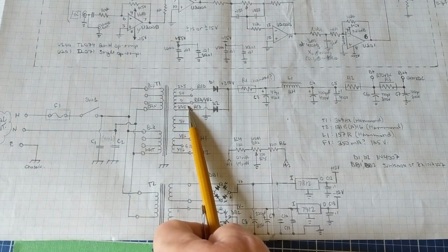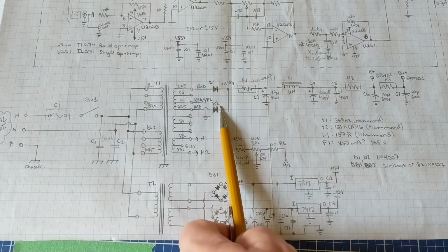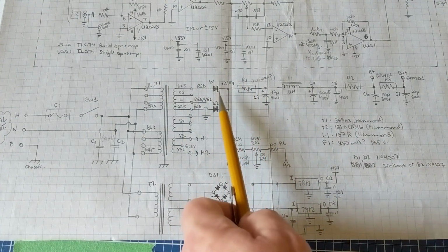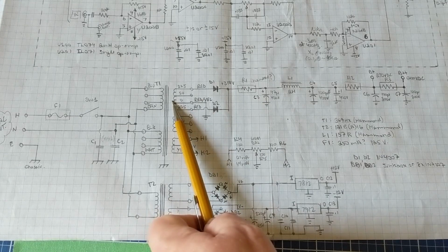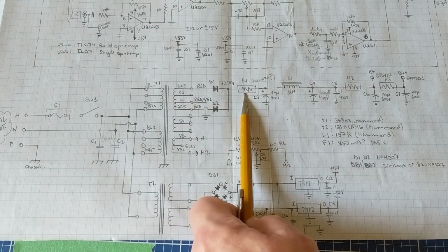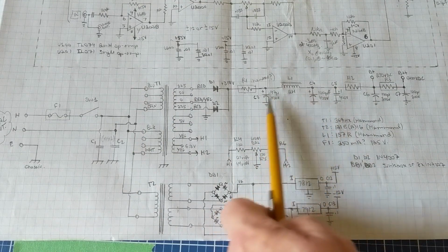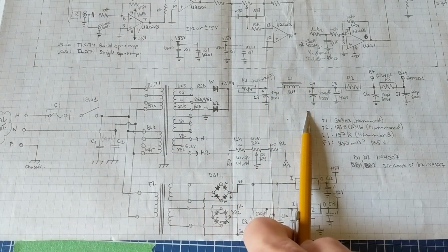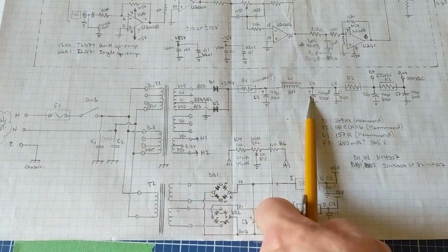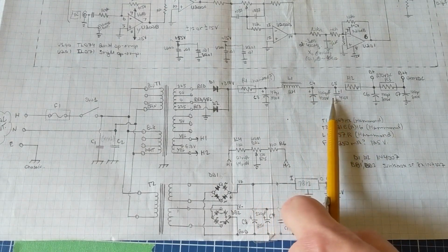For the high voltage tap secondary, I'm using just a standard dual diode stage here to get a 120 hertz rectified signal coming off the transformer. It goes through a ballast resistor to minimize the current surge when it's first turned on and the filter capacitors start charging. This is a standard pi network filter, so we have a capacitor, choke, capacitor to provide optimal filtering. I've added a smaller 0.1 here to get rid of some of the noise.